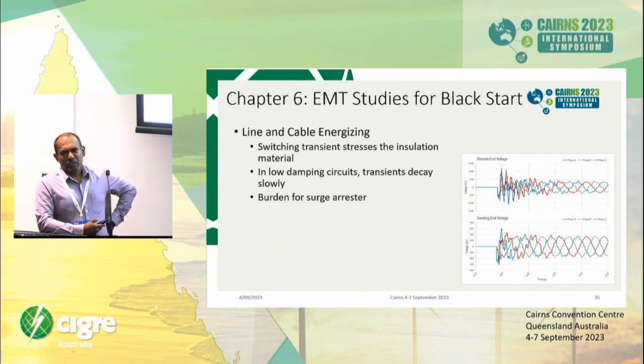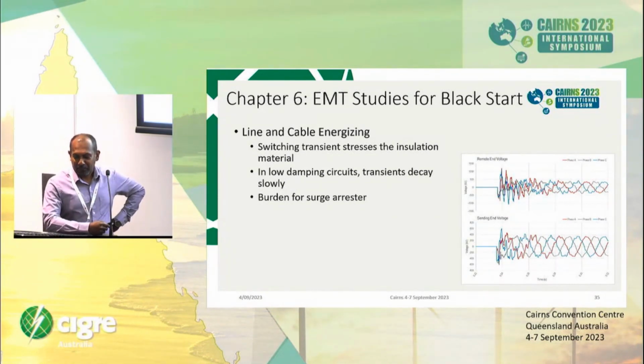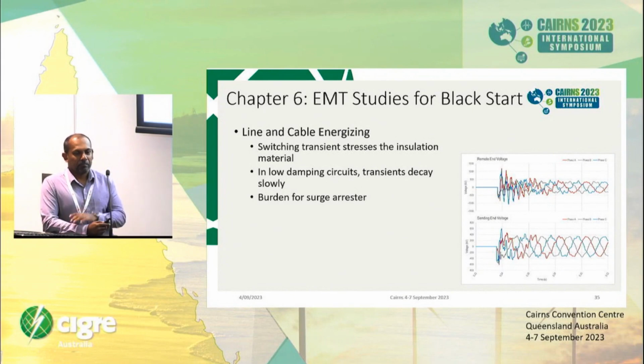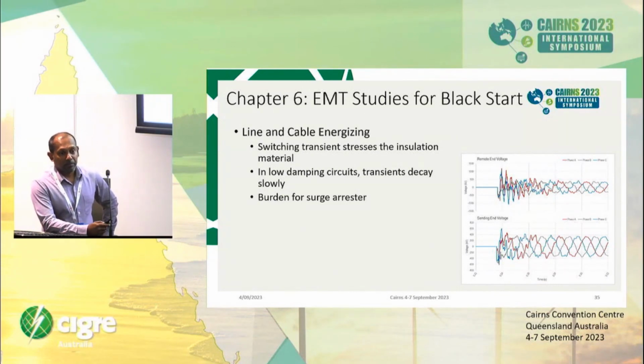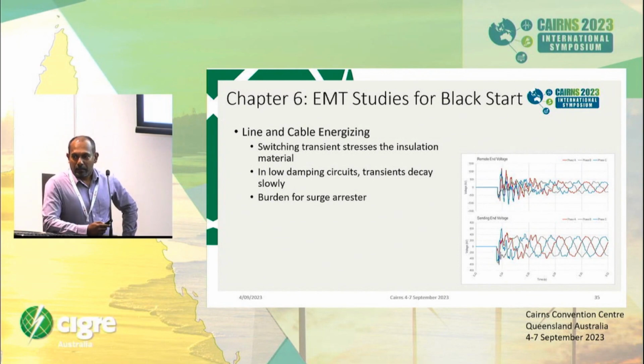The high frequency switching transient is another thing, but definitely these things will be done during the normal design stage. I'm not thinking this will be a big issue for the black start restoration process. We always expect people have done due diligence during the design stage, and they sized the surge arresters, and they evaluated their switching transients or SOV properly, even under very low short circuit conditions, which will give you some protection during the black start process.